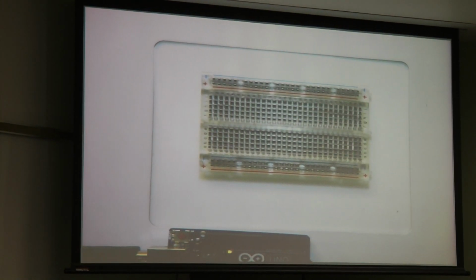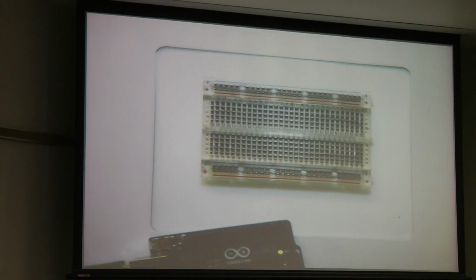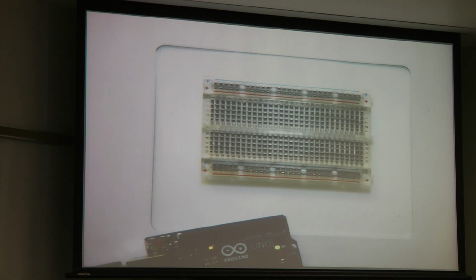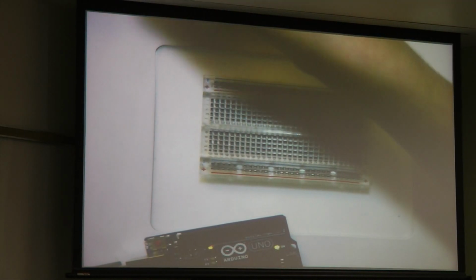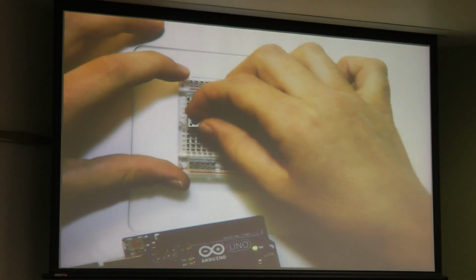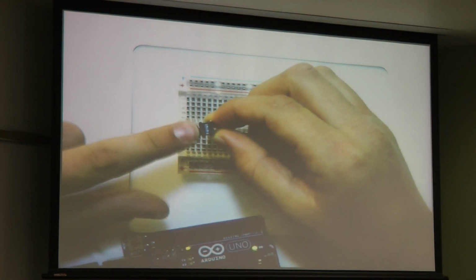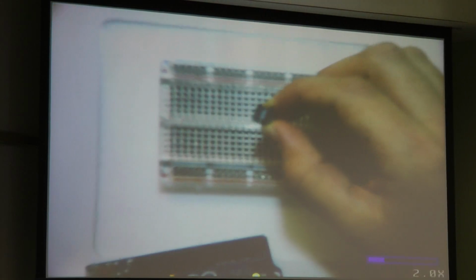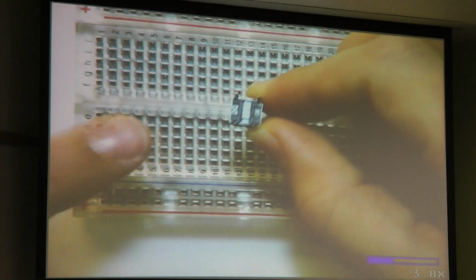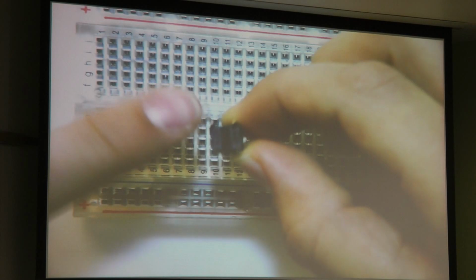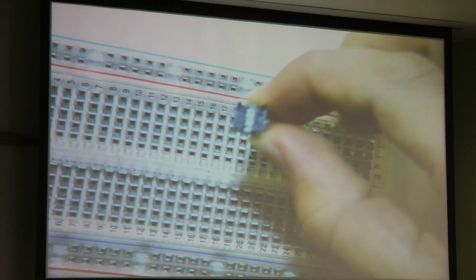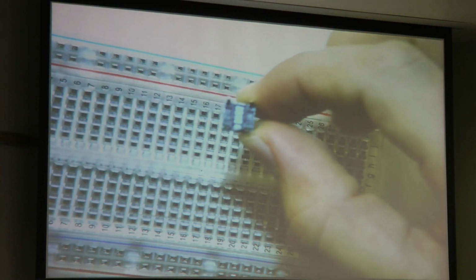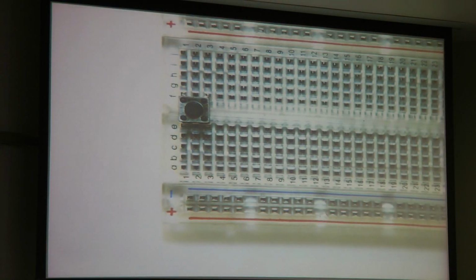So what we'll do is we'll get out our jumper wires. And the first thing we'll want to do is get out our button, because we'll be using that. So in here, we'll open up our button. This is a button, and the way it works is that you'll notice this side is longer than this side. It's because the pins are connected this way and this way, and then when you press it, it connects them this way. So we'll insert this across the well right here, and push it down. Sometimes the buttons don't always stay well and they'll need a little more pushing.